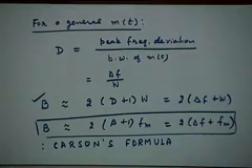Now again, in these general cases also you can see that whether you will have narrow band FM or wide band FM will really depend on the value of delta F. That's another way of looking at it. When beta is large, delta F is large, and you have wide band FM. So the important point is when delta F is large, the bandwidth will be governed largely by the peak frequency deviation, and that makes a lot of intuitive sense if you think about it.